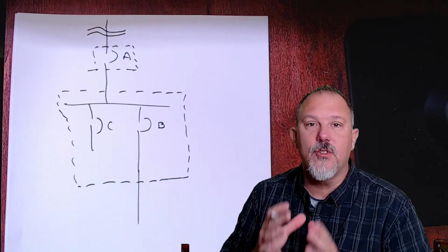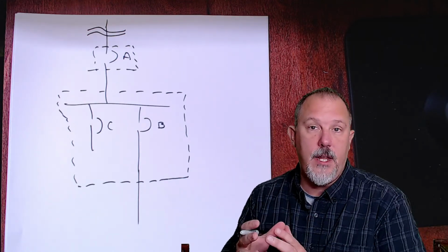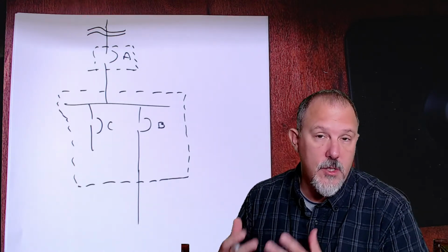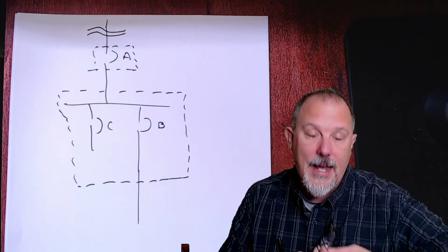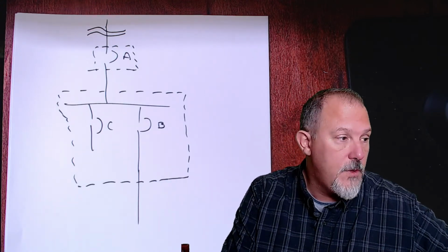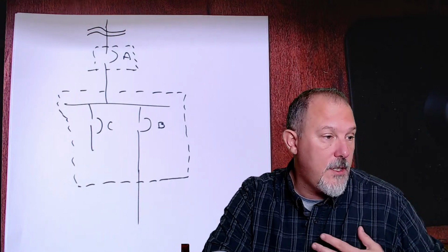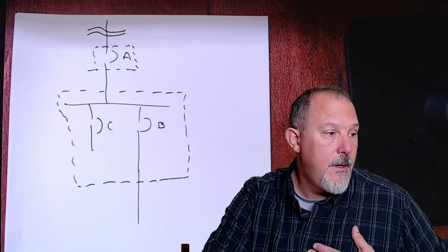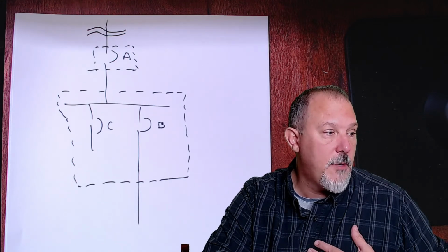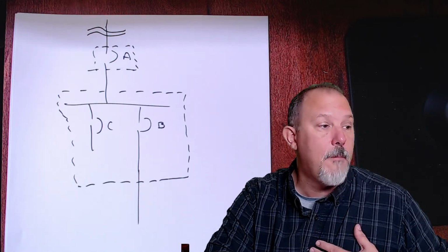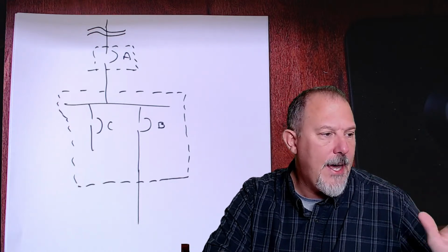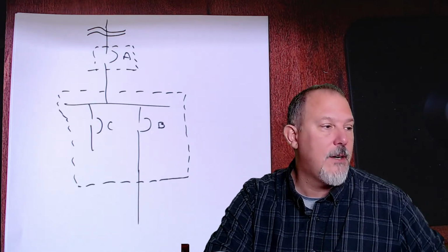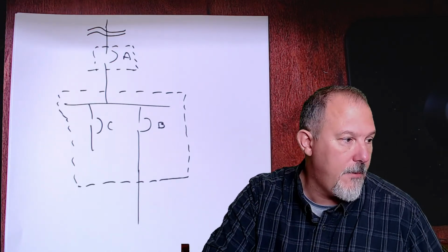Putting those dashed lines around the equipment helps us understand a little bit more than just the power flow through a power distribution system. So that can add value to the single line, and JW is saying that here. Otherwise, no way to tell if a switch is in the same enclosure, a separate enclosure, right next to you, or a mile away. He says, I've had it happen where you are planning a service job and you really can't tell. And I'm with you, brother. I am absolutely with you.